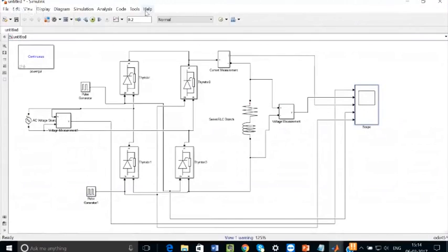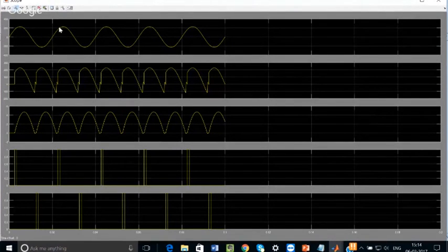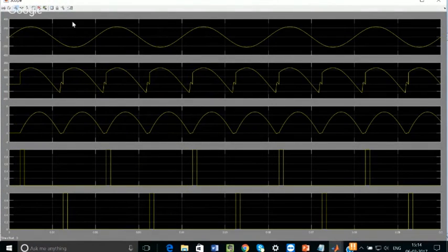And if I want, I can just show you. Here 10 cycles are coming. In 5 cycles, it will be a little more clear. So here you can see this is the AC input 230 volts what we gave, and in that you can see the voltage across the load. So this negative region is because of the inductor. At this point the thyristor gets commutated, but the thyristor will still conduct. That is because there is an inductor in the circuit. We have put an RL circuit.